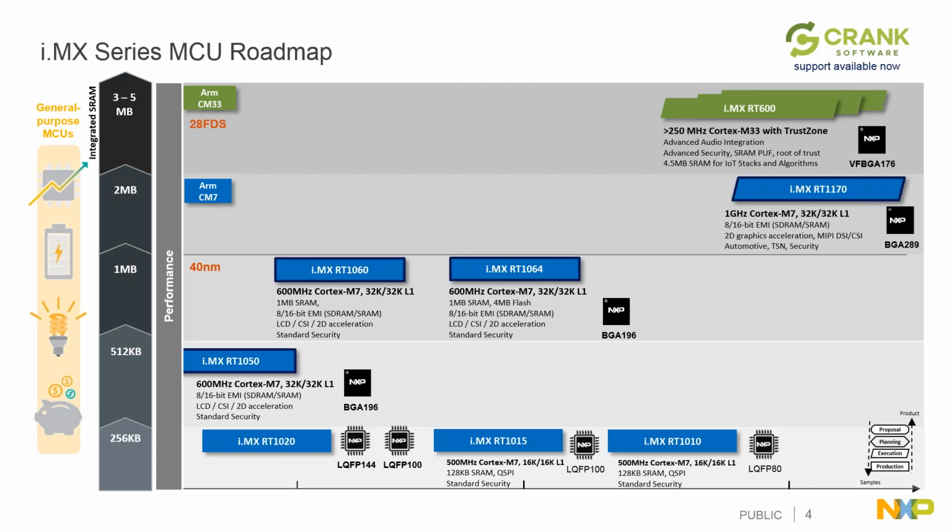First, it supports high performance real-time processing. It can operate at a core speed of up to 600 megahertz and has very fast responsiveness with an interrupt latency as low as 20 nanoseconds. Second, the i.MX RT 1060 supports product designs that include advanced multimedia for graphical user interfaces.